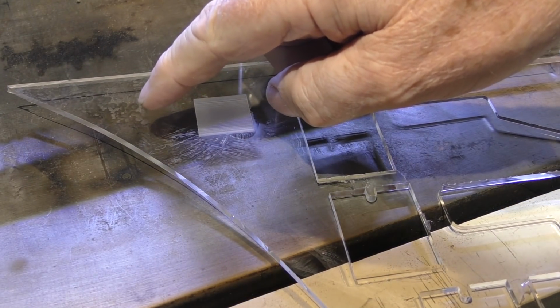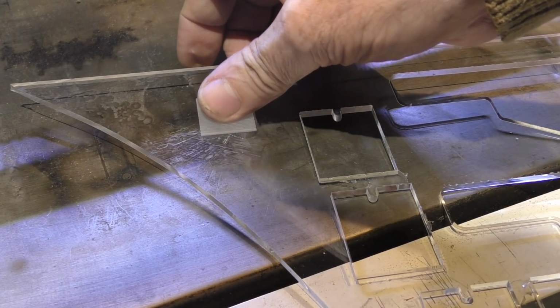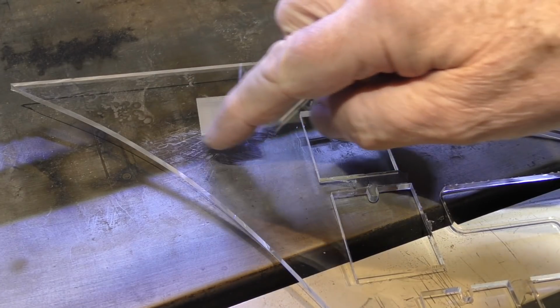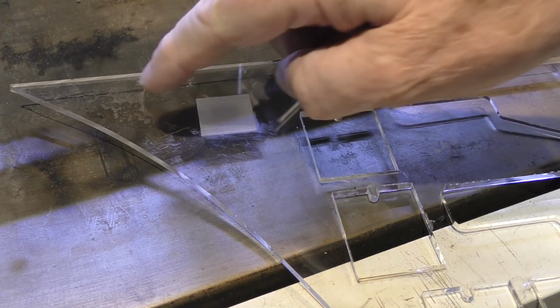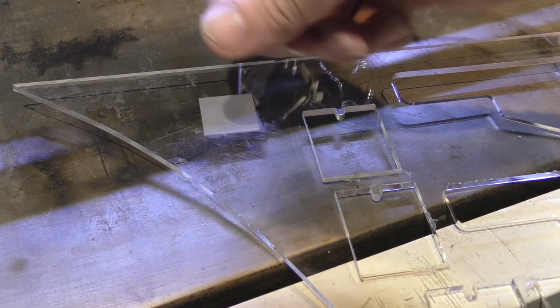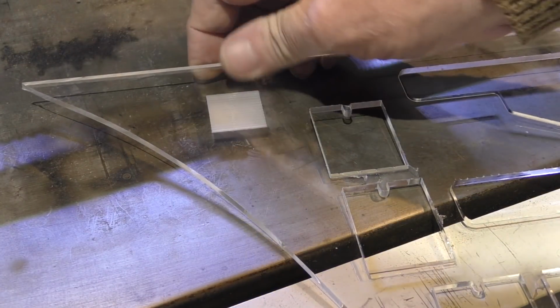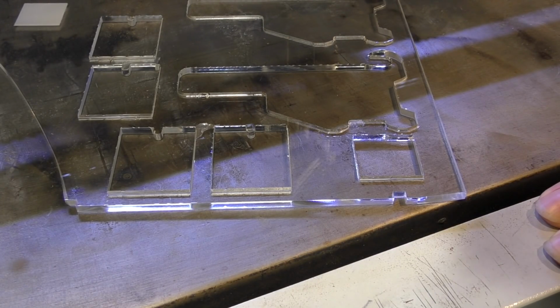I mean, and also the other telltale thing that I only get when I do very, very faint engraving, and this is not faint engraving, is look, see the settled acrylic condensate? It's already cooled and it's condensed as a powder. It's no longer bonding to the surface. Look, it just wipes off. Not only am I demonstrating to you, I'm discovering things that I hadn't really discovered before.